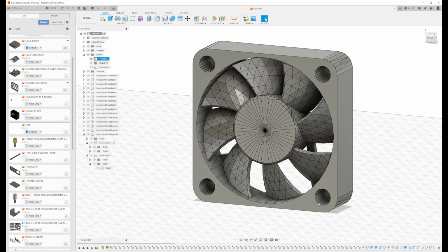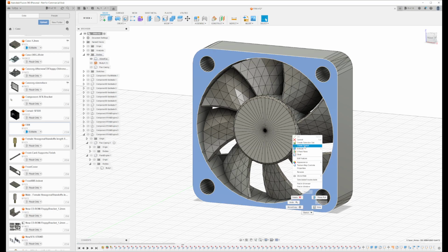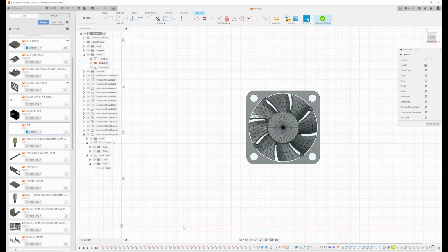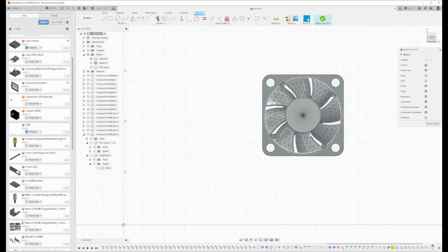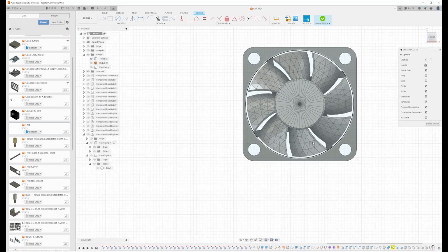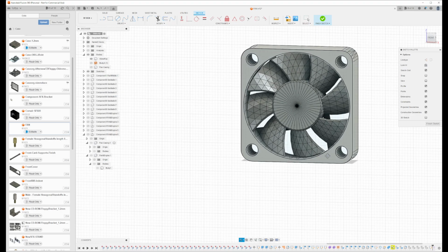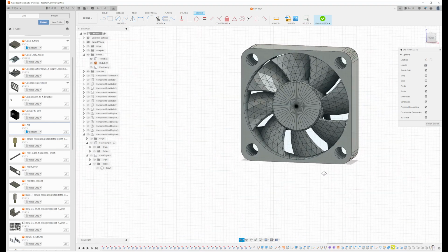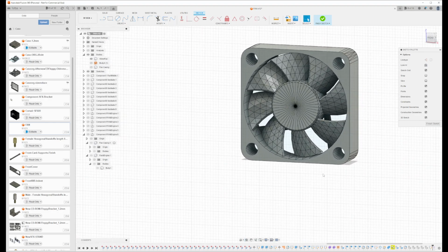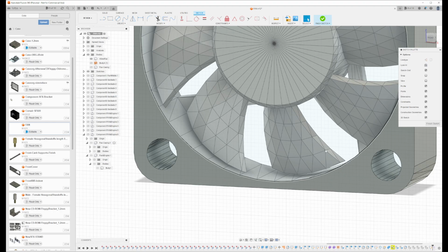So you start by making a sketch on any surface. For instance, I use the front here, or I use the back here. I would prefer to use the front, and then you create a sketch. The main thing here is that you just need an object that exists in 3D space. You see this exists in 3D space. Now you go up here, and you tick for 3D sketch. What happens then is that you can make the sketch in three dimensions, and an object like this would have